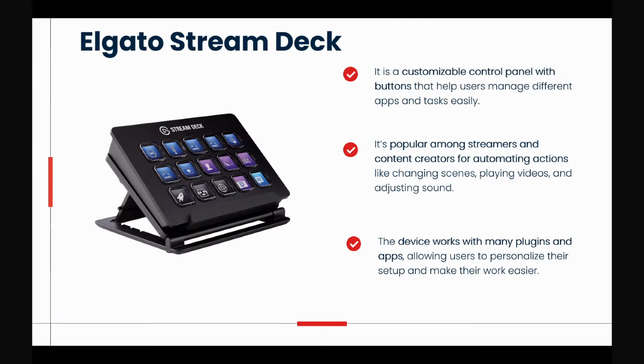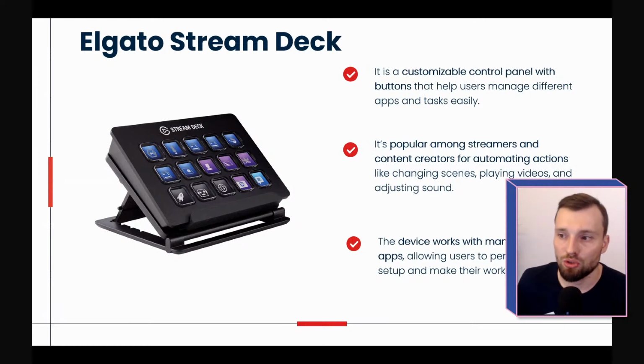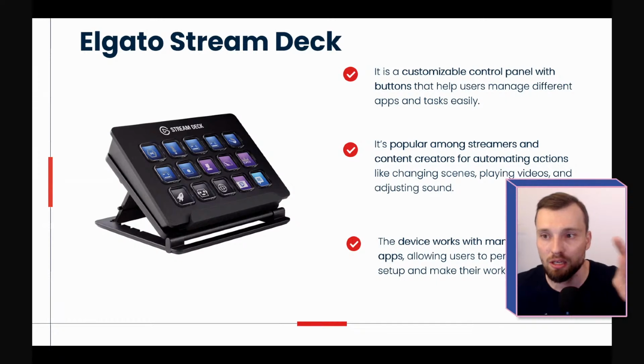And I would like to show you 2 use cases of how we can use it. First case, because I didn't mention the batch utility in Navisworks, I'm going to use batch utility in conjunction with Stream Deck in order to create a federated model. And the second example will show how to automate actions in Solibri using Stream Deck by just clicking on one button, okay?